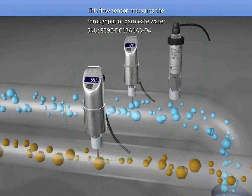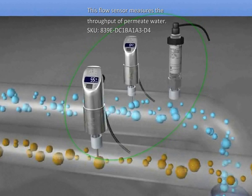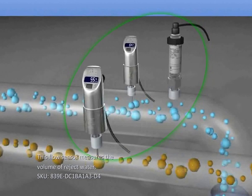On the output side of the filtration skid, we have 2 flow transmitters, one on the permeate water pipe and a second on the reject water pipe. Both the 839E flow sensors have been individually calibrated for high flow and low flow settings based on the diameter of their respective pipes. The flow sensors at the output end of the process are used to measure the total throughput of the filtration system in gallons of water.